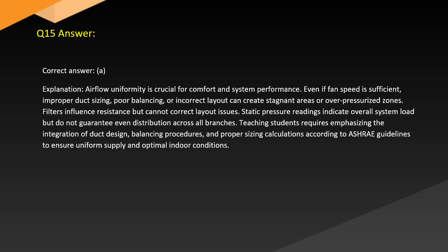Static pressure readings indicate overall system load but do not guarantee even distribution across all branches. Teaching students requires emphasizing the integration of duct design, balancing procedures, and proper sizing calculations, according to ASHRAE guidelines, to ensure uniform supply and optimal indoor conditions.